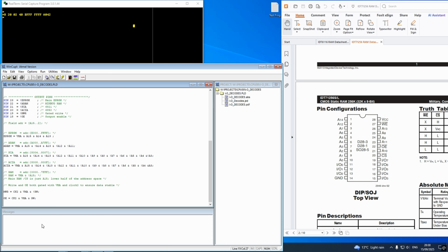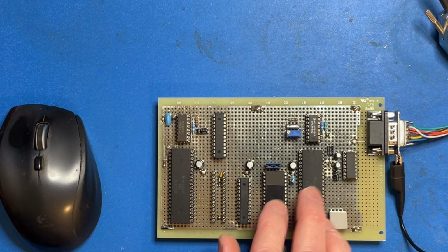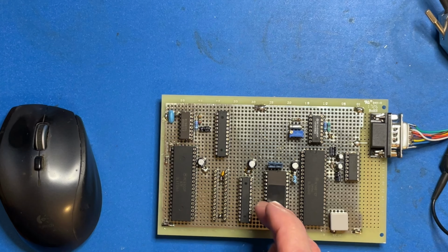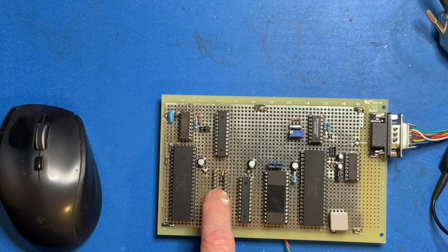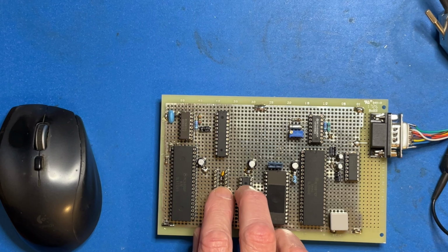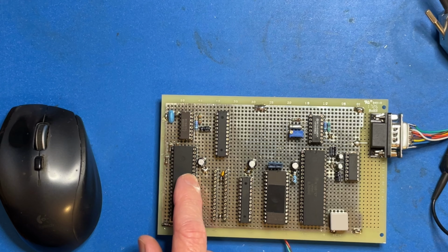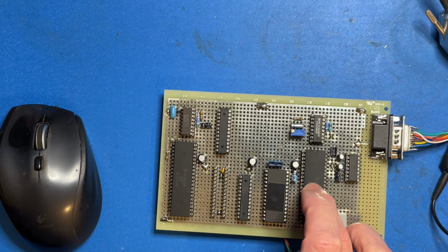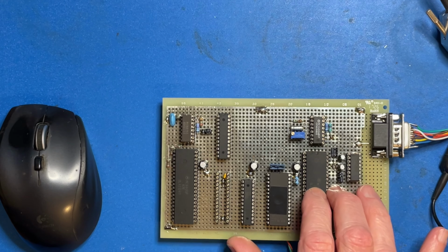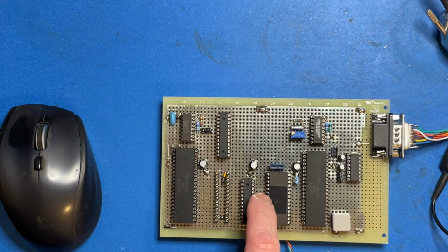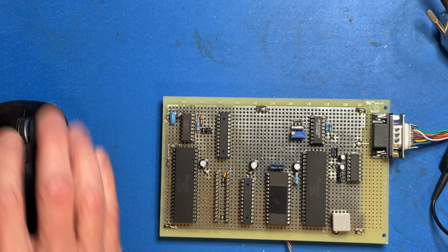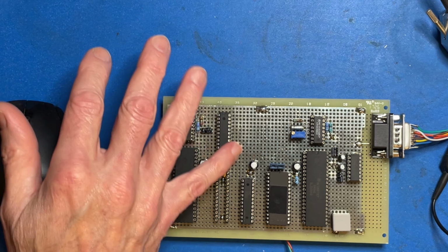So, I've done a couple of minor wiring mods to take the direct read-write signal from the CPU off the write line on these, well, both sockets. Instead, that only goes to the decoder PAL and the PIA, the original wiring as it was intended there. And now the write line to each of these comes from the gated write from the PAL.